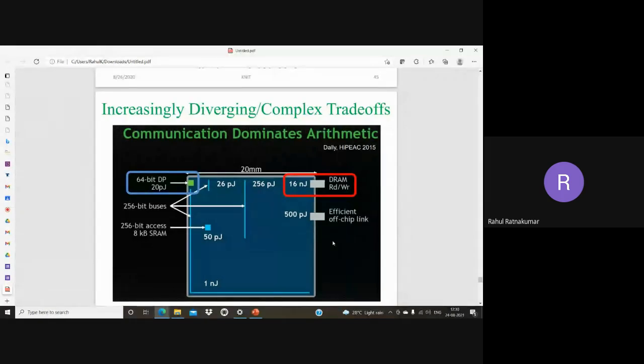They also cause some delay, right? RC delay. And there is some capacitance. We have a tau, or delay, time constant. Delay is R into C. So resistance increases, delay also increases, and the capacitance also increases. Then delay significantly increases. So there are a lot of problems happening when we scale the chip to a lower or advanced technology, from 12 nanometer to 7 nanometer, our resistance is increasing.